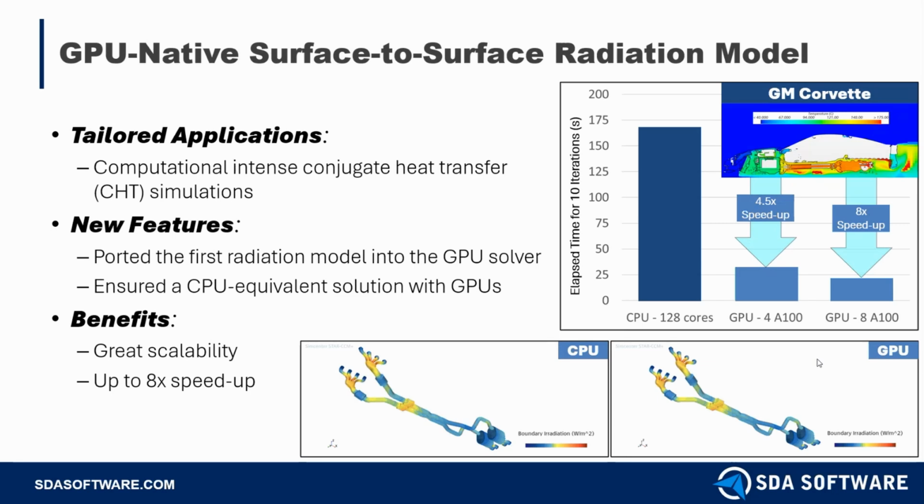Commonly, CPU solvers suffer from poor scalability at high core counts. So in order to have comparable performance against the A100 GPU solution to gain that speedup, more than 8 times the CPU cores would be needed, just due to the scalability limitation of the CPU solver. But if we look at a GPU solver, it is showcasing promising scalability, where doubling the GPUs from 4 A100 to 8 A100 nearly doubles the speedup.